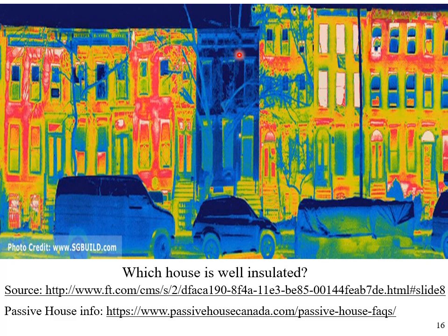And that's possibly correct, but probably not, because just around the entrance door and some of the windows, you can see some heat that is managing to escape. And you'll notice that heat is also escaping at the highest points and less at the lower points. This has to do with how hot air rises, which means you have that stack effect.